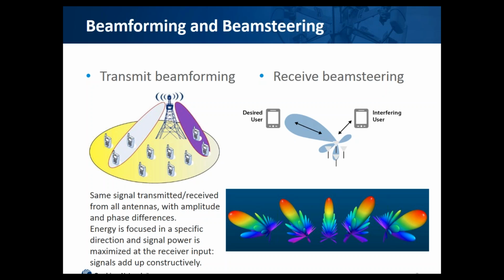When we use multiple antennas at the receiver in this type of configuration, we talk about beam steering. Essentially, the beam steering receiver shifts the received signals according to the shift that occurred in the propagation channel to align all the signals so that they add up constructively. This is the same as steering the beam towards the desired user.